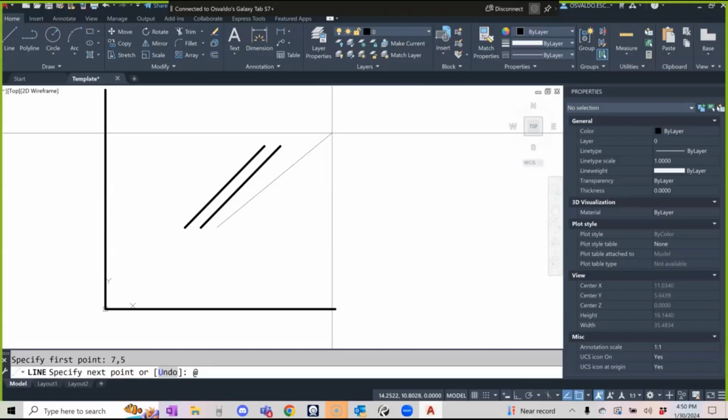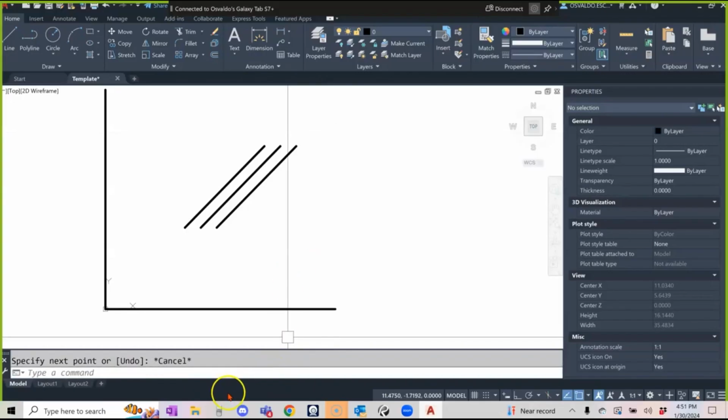This is the add. How do you type the add? You type the shift 2. Shift 2 will get you the add symbol. And then you just gotta tell it how much you move in X and how much you move in Y. In my case, I'm gonna move 5 and 5. Boom. To be honest, I like this one better, so I don't have to go back and forth with this dynamic input. Because every time that I want to do something relative to wherever I am, I can type add 5,5, add 10,5. You guys understand what I'm saying? Okay. That is the alias.